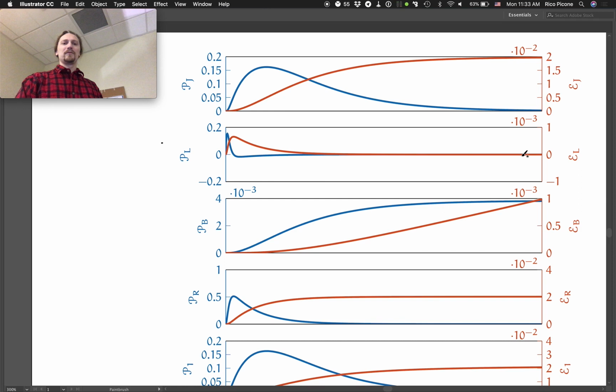Yeah. So is that kind of like damping the effect of the motor? Because when you attach the voltage, it's instant, and this is making it less of a shock to the system. Or what is the inductor doing? Well, if we could get rid of the inductor, we would. We would love to. But it's not actually a component we put in. It's an effect of having the armature coil windings. We had to do the windings so we could get that electromechanical force, the Lorentz force, to happen. We needed to create that magnetic field.